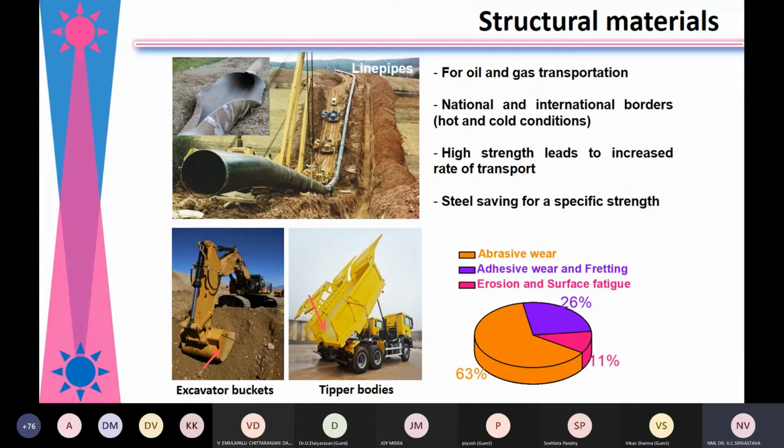And to withstand that pressure, the strength of the material used in pipelines has to be high. And in such cases, with new developments in line pipe materials, we have now reached around X120, very high strength material with high toughness. So these are the areas, like wear resistant materials and line pipe steels, which demand so many different properties.